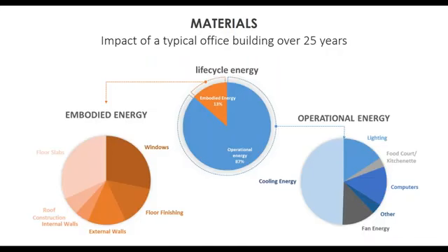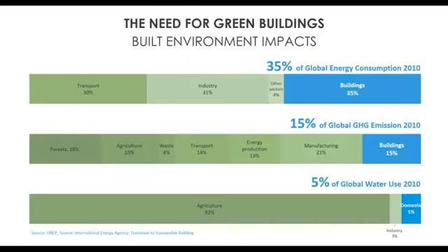It's important to understand the embodied energy versus operational energy in buildings. For a typical office building, around 10 to 15% of the energy use is from embodied energy, while operational energy savings are very important. It's important to understand the critical role of embodied energy. So the indicator used to measure this is obviously embodied energy materials, which you'll see in the EDGE app, and we'll cover that. So these three items or criteria categories, energy, water, materials, are what make up the EDGE tool, which we'll see in a second.